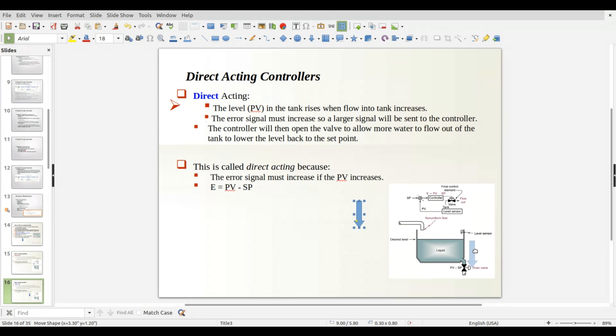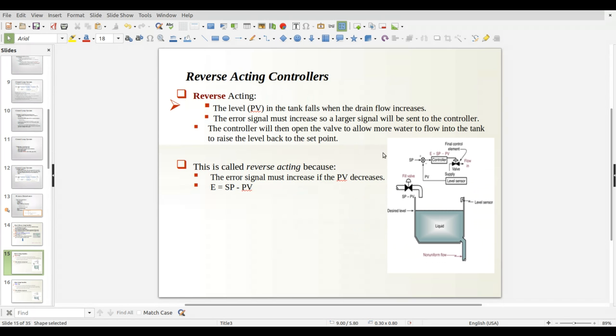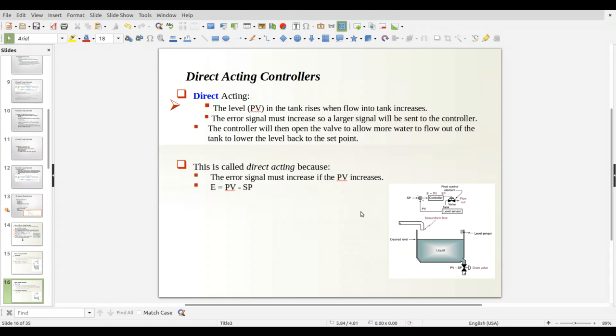The valve here is our control in this particular system, right? We can open or close the valve more or less, and so that's our control. So the question is whether the control is up here, or down here. All right, and that's the difference between the direct and reverse acting; basically, where is your control at.